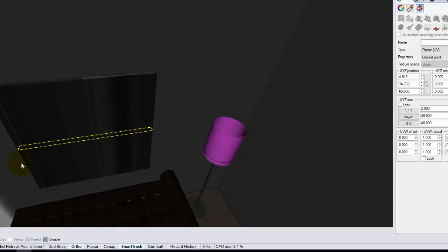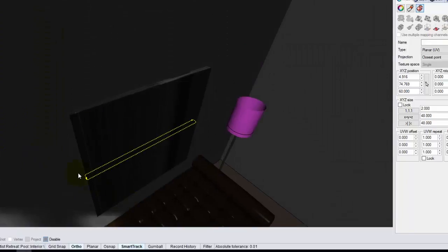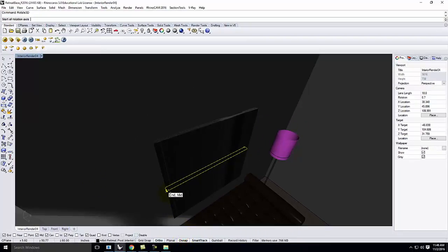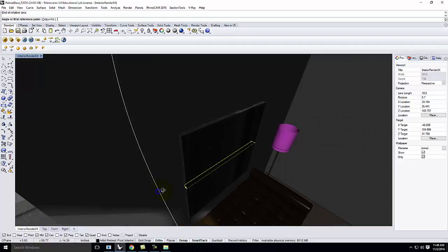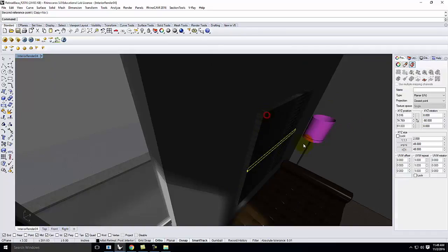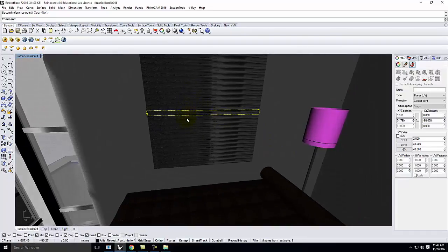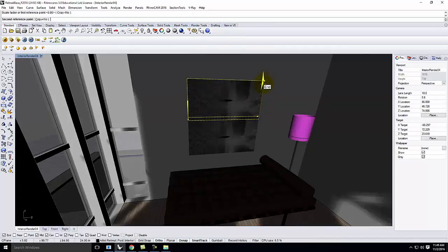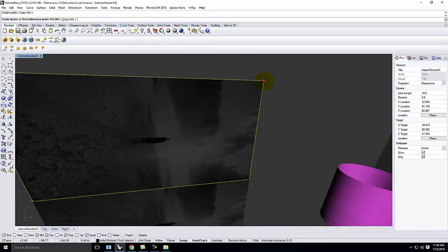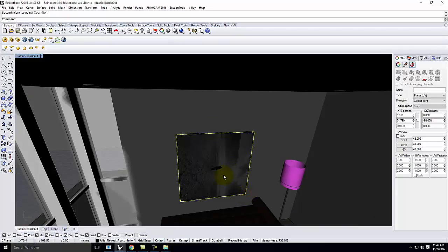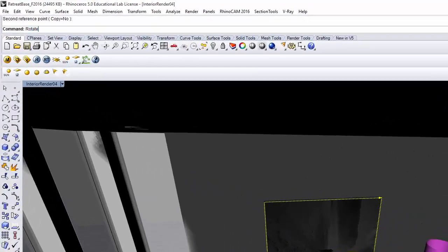I've shown the mapping. Go ahead and rotate 3D. Turn on my snaps. We want it to be up in that direction. Obviously, it's repeating too many times, so let's scale 1D. Move it up to the top. And we'll scale 1D and move it down to the bottom. Like that. It's obviously on its side, so I need one more rotate 3D.